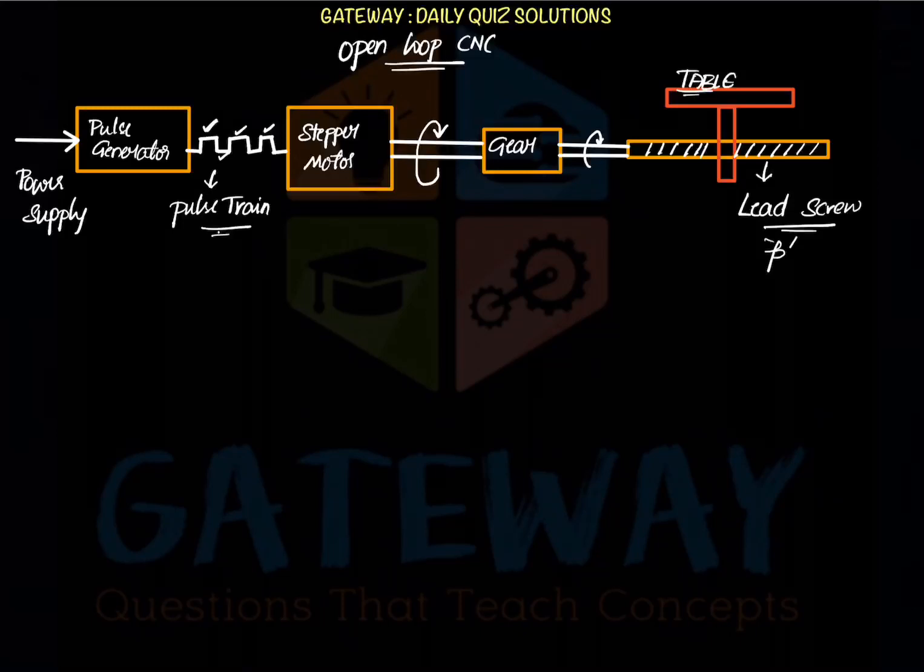The lead screw will have some pitch, and the lead is nothing but the distance traversed by the table for one revolution of the lead screw, and that will generally be equal to the pitch of the lead screw. And we know what the pitch of the lead screw is. It is the distance between two consecutive crests or two consecutive troughs. This will be the pitch. This is all about the functioning, and we'll see how it functions.